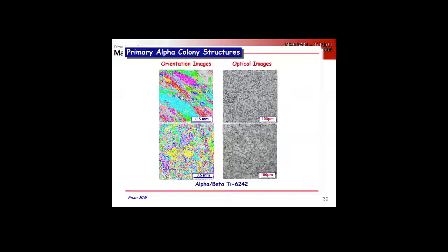On the grain boundaries, it's going to be where you have a plastically soft grain next to a plastically hard grain, one that's well oriented for slip next to one that's not. Through cyclic loading, you're going to have a pile up of defects at that interface that's potentially going to lead to nucleation of damage. And then the crack has to propagate.